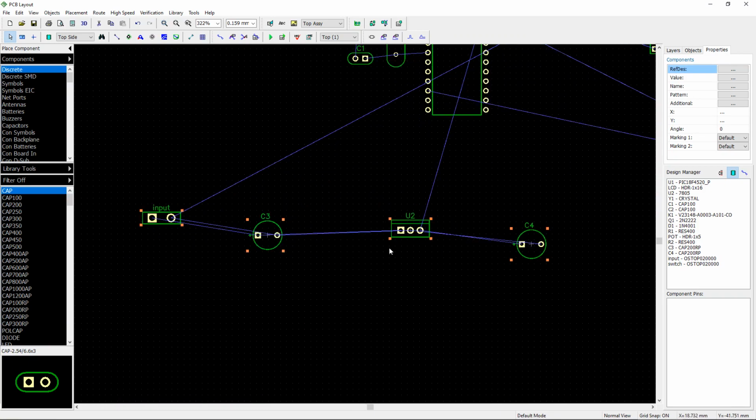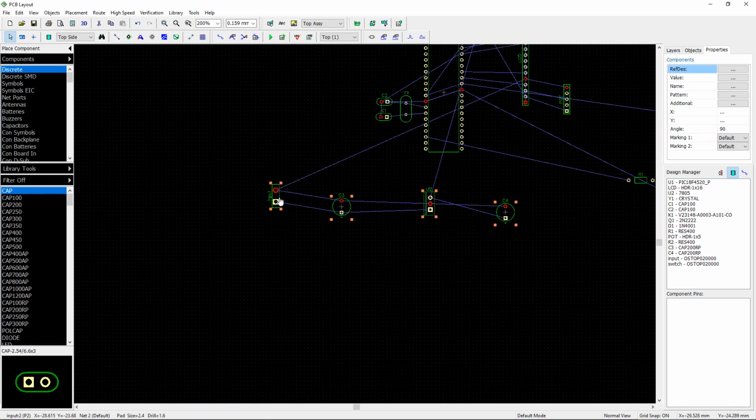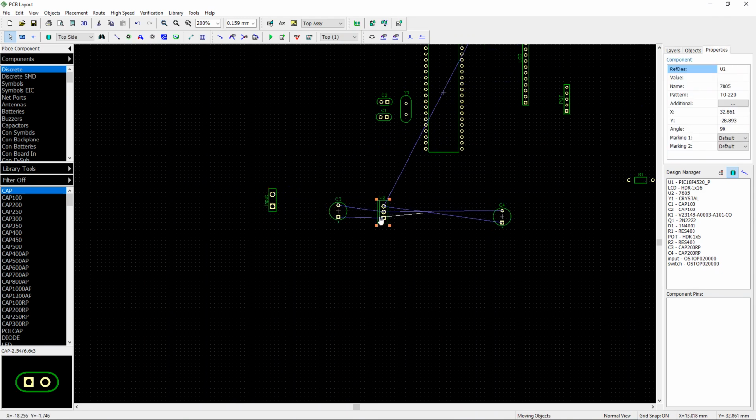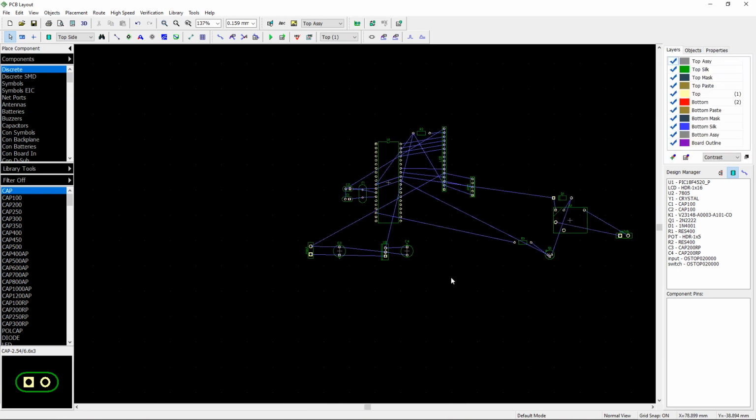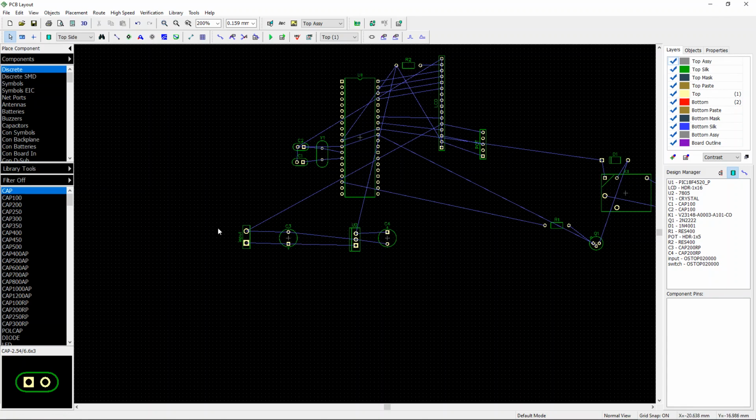Then for those who are more interested in why we are placing the components where they are, we have a PCB lecture PowerPoint that you can just ask for and I can give you, and you can actually understand why we're doing some of these things, like why is the power here. There are design rules why we do this, like sections which have the same functionality, for example power circuitry must be confined to a specific location. You cannot have your power components spread all over the PCB. That is a bad design. And as well, there are things like heat sink placement and so forth.